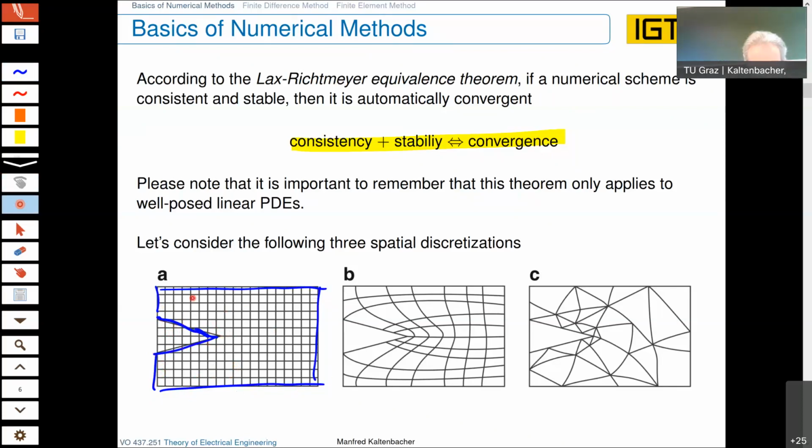Another possibility is here B, and the possibility B is you still try to have quadrilaterals, meaning elements with 4 nodes, as you can see here, and you somehow really take into account that this triangle is cut out. But you see, you have very different elements here with different sizes. If this is good, we have to discuss.